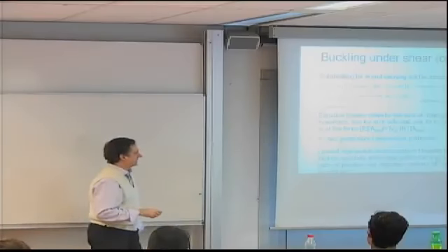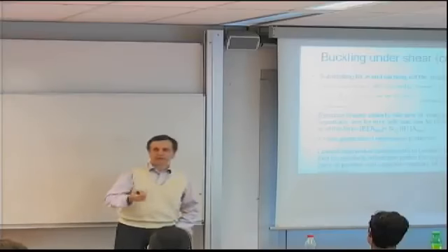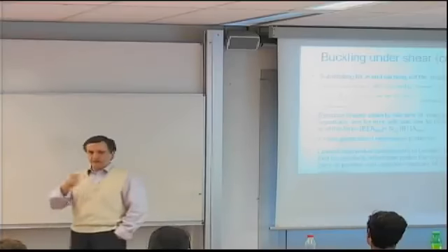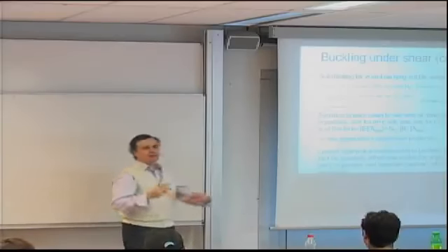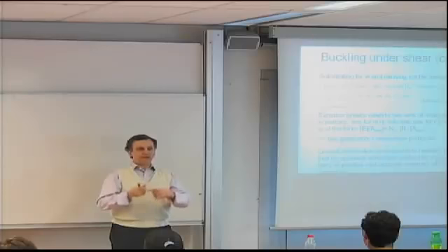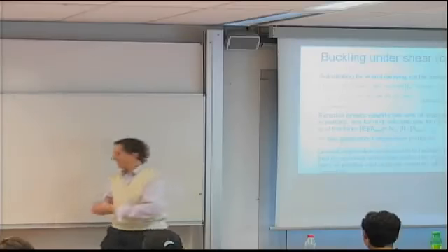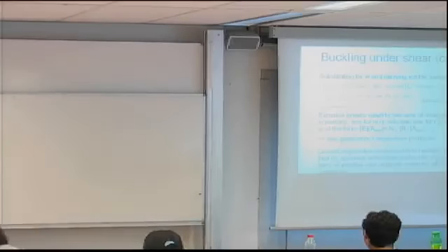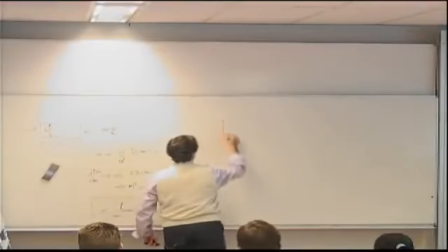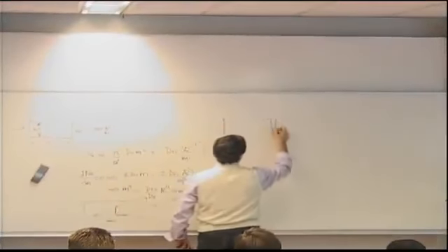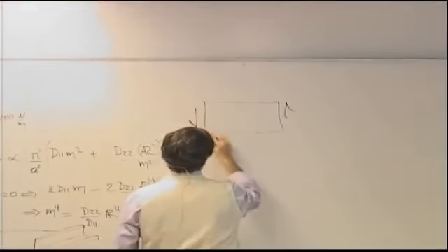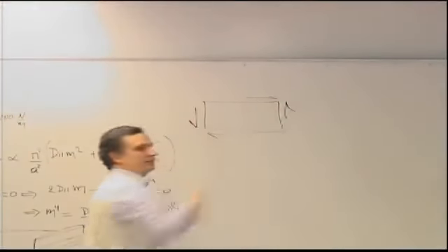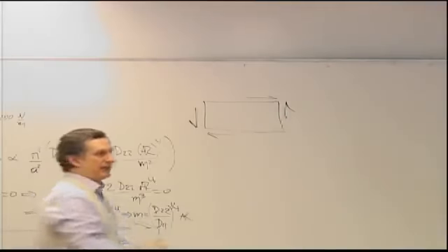And in fact, you will find that if you have a specially orthotropic plate, specially orthotropic meaning B matrix is 0 and D16, D26 are 0, then the eigenvalues appear in pairs, plus and minus of the same number. That means if I apply a shear load, I get one buckling load if it goes in one direction, and if I change the orientation, so let's say this is positive shear, I get a buckling load.